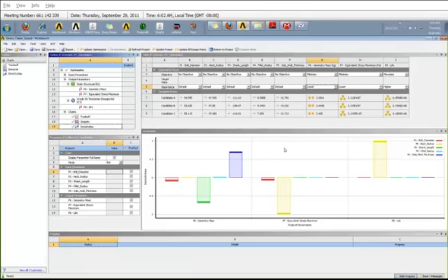The sensitivity chart lists, for each of these output parameters, I have an output parameter for my weight, stress, and my life, I can look at how the input parameters affect my output parameter. Basically, it is sensitivity going from +1 to -1. Let's take a look at the sidewall thickness over here. The sidewall thickness has a positive sensitivity to the weight of the part, meaning if I increase the sidewall thickness, then the weight of the part increases.